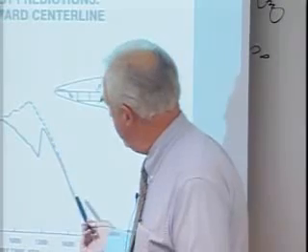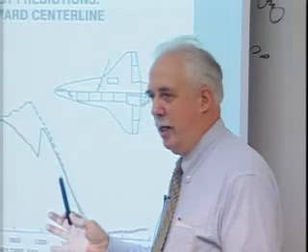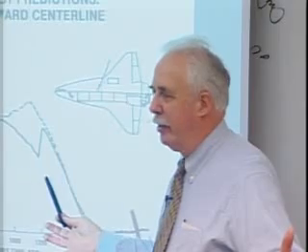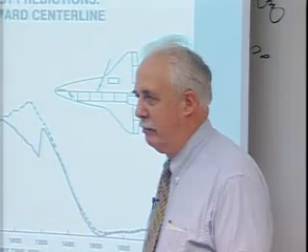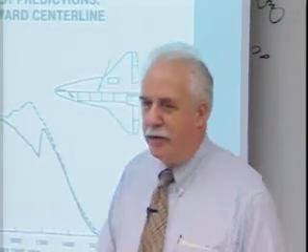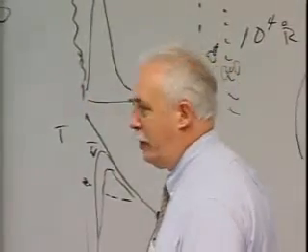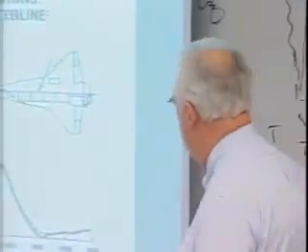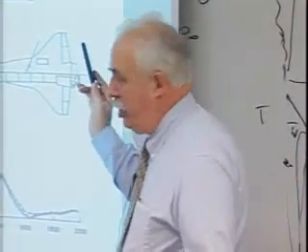And that even works with a normal shock Reynolds number. When you go back and look at all of the shuttle data with a crude, back-of-the-envelope normal shock, local heating to reference heating, including turbulence, it's amazing. It really is. First order physics seems to hang in there, in spite of all the complications of chemistry and all kinds of things that can happen. You have to be careful, but overall things usually work for you. Again, that's academic there. If we put in a constraint, that would look a lot better. Okay, that's good stuff. We can do even better now.